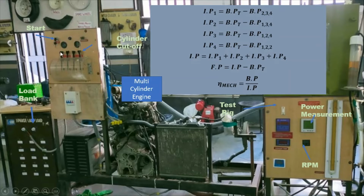Now the first cylinder is cut off. Short circuiting a spark plug can do this. Reduce the dynamometer load so as to restore the engine speed with the help of the accelerator. Record the dynamometer reading for the brake power calculation. Connect the cut-off cylinder and run the engine on all cylinders for a short time. This is necessary for the steady state condition. Repeat the steps for cutting off all the cylinders.